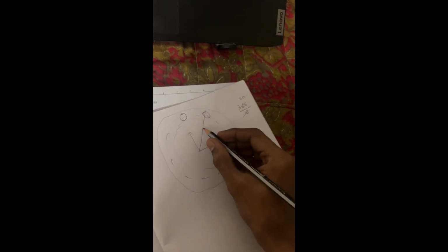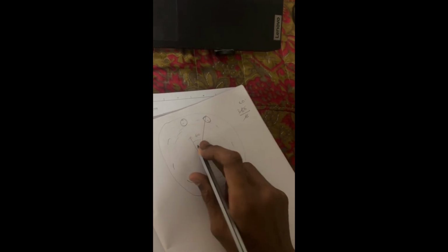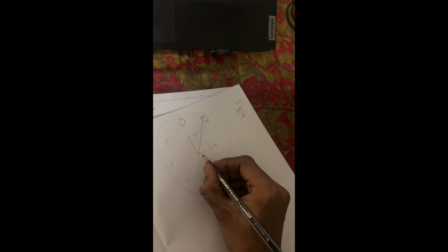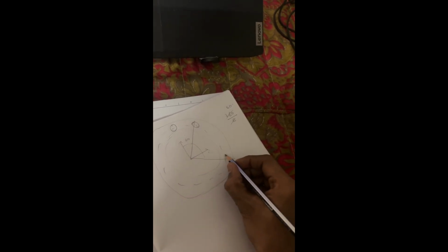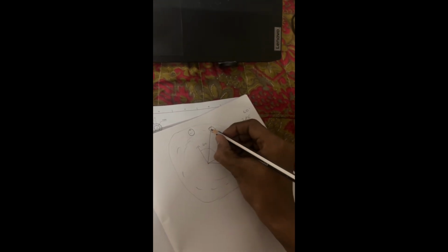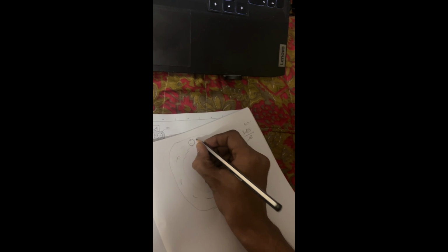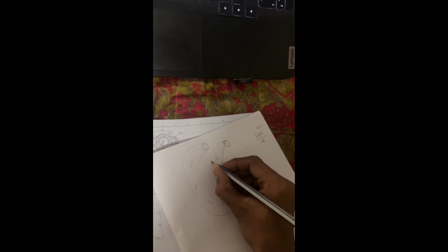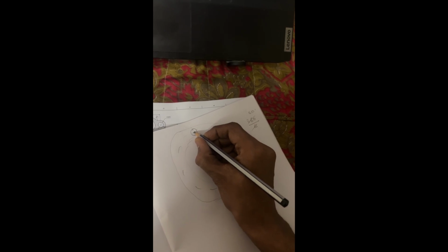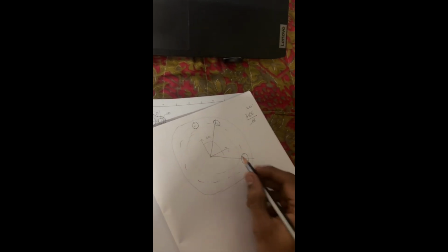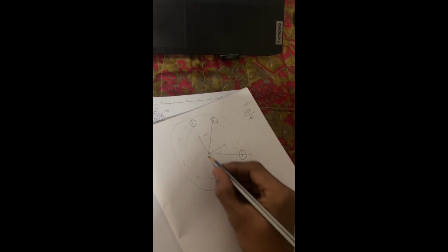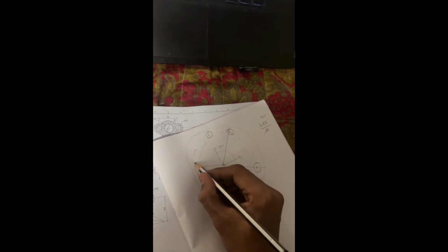And after this, from this point to this point is 60 degrees, and from this point to this point there is another circle at 60 degrees. Let us assume this point is here, it is at 60 degrees. This is the third point. Please make sure that the center of these small circles is at the intersection point of this axis line and this point converging here. Similarly, as per these 3 circles, draw the remaining circles, like 4, 5, and 6. By this we will get all these 6 circles.